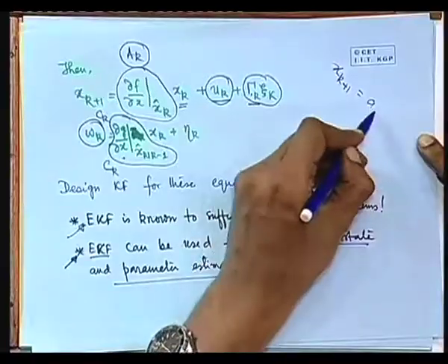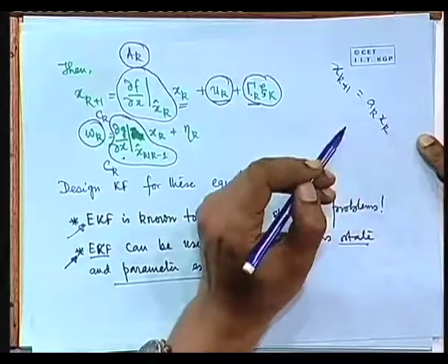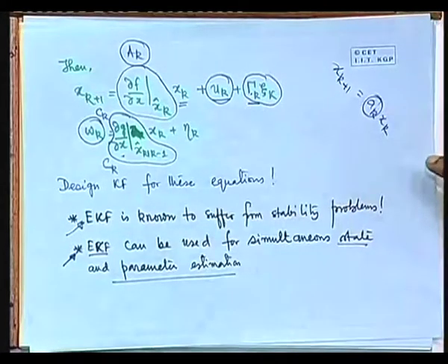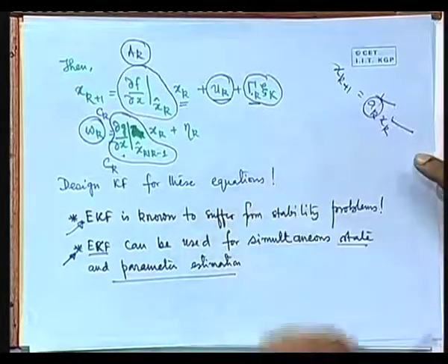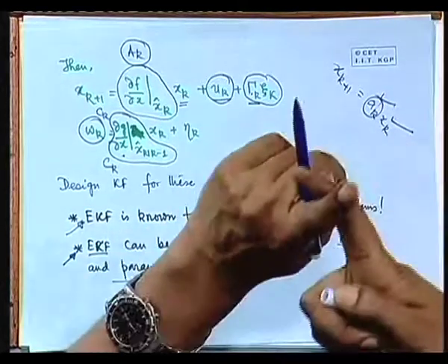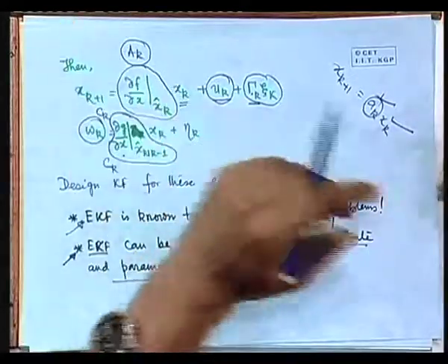So then what do you do? You have to simultaneously estimate the state and the model parameters. If you want to do that, the model x_{k+1} = a_k x_k is linear if a_k is known, but completely non-linear if a_k and x_k are both unknown, because you have a product of two unknowns. So it is a non-linear model.